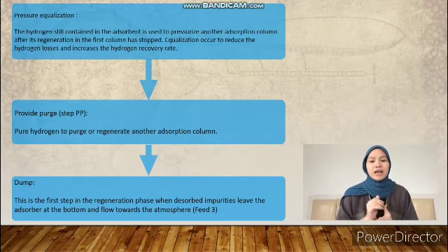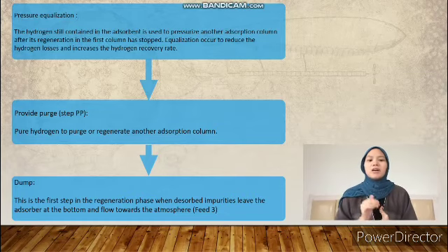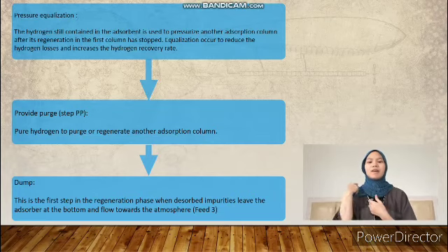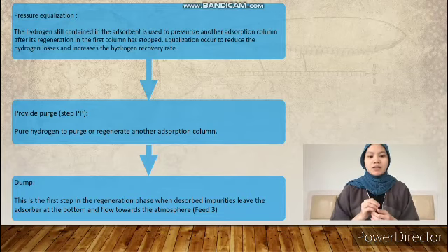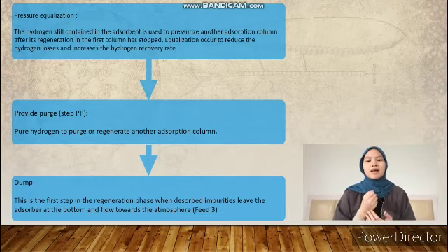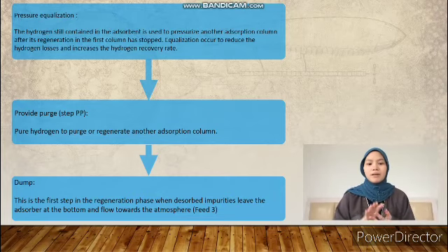The purified H2 is recovered at the top of the column with a very small pressure drop. After a certain time, the adsorbent is saturated with CO2 and the column needs to be regenerated by reducing the pressure, where the column is fed with the reformed gas at low pressure in order to complete the adsorbent bed regeneration.